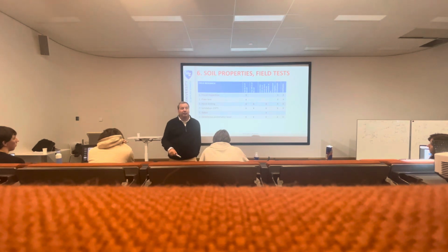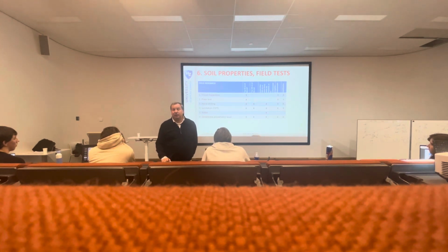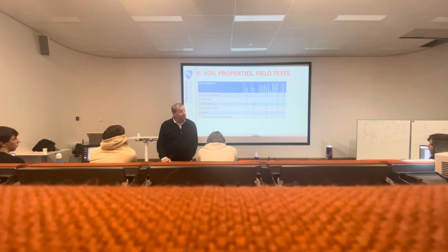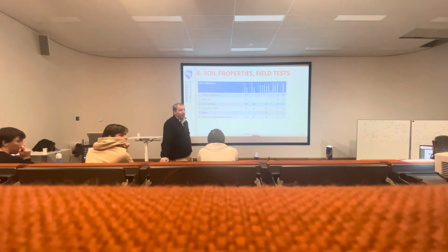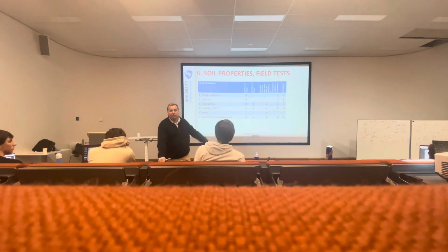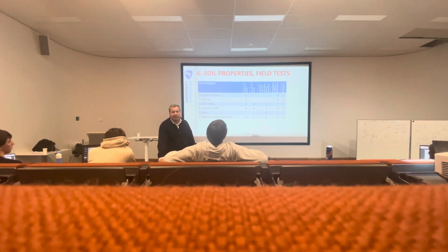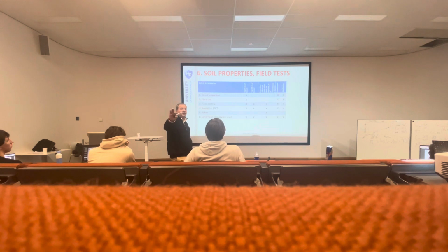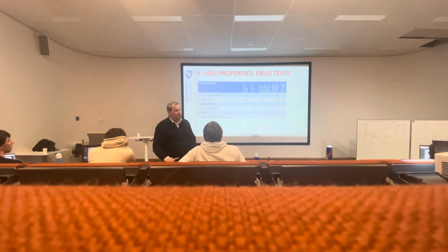Also check the existing buildings and existing roads. Because when you see cracks on buildings, what does that mean? Do we have sand or clay? Clay. All agree clay? So when we get more cracks, etc., that's bad news. There is clay and it consolidates. There is still consolidation. On a road, when we see movement like this, then we can also see there must be some clay beneath. And then there are some tricks to see how deep the clay is. That depends on the length of the waves. But that is a little bit tricky. But still you can see that. So a visual inspection tells us a lot.